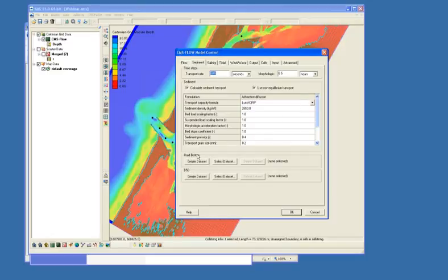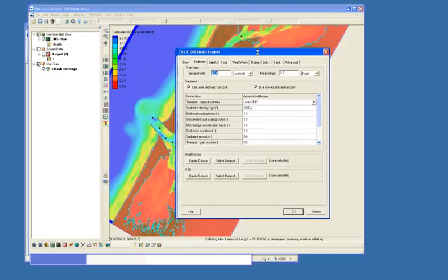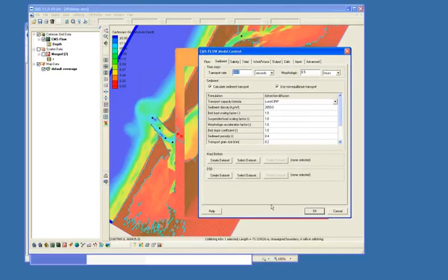The hard bottom data set is, in some areas of the country there may be a rock undercropping under the sand where the sand can only erode down to a certain point. And this data set for hard bottom is how we designate those areas to be located.